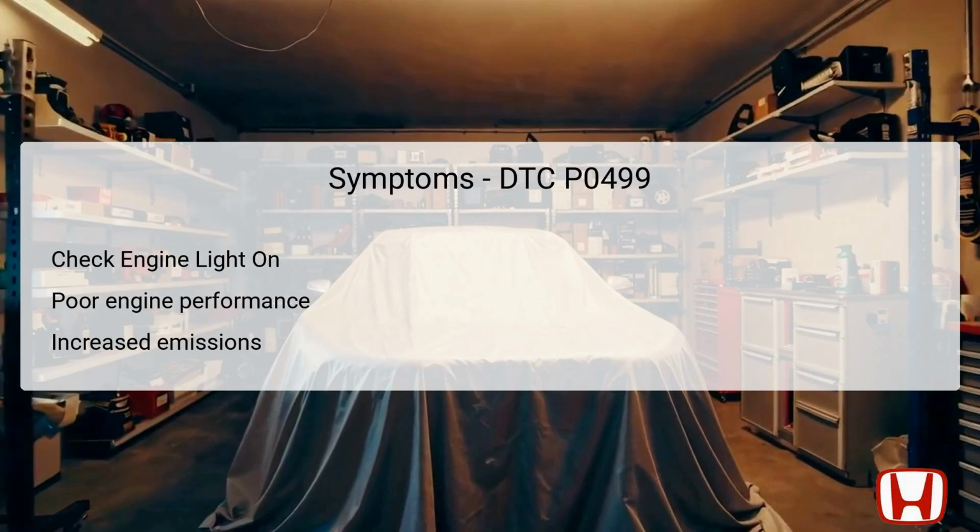Drivers may also notice poor engine performance, which can manifest as rough idling, stalling, or reduced power when accelerating. These performance issues arise because the faulty vent shut valve affects the air-fuel mixture and combustion process. Moreover, an increase in vehicle emissions can occur due to the malfunctioning EVAP system failing to contain harmful vapors. Collectively, these symptoms highlight the importance of addressing the underlying cause of the DTC to ensure both performance and compliance with environmental regulations.